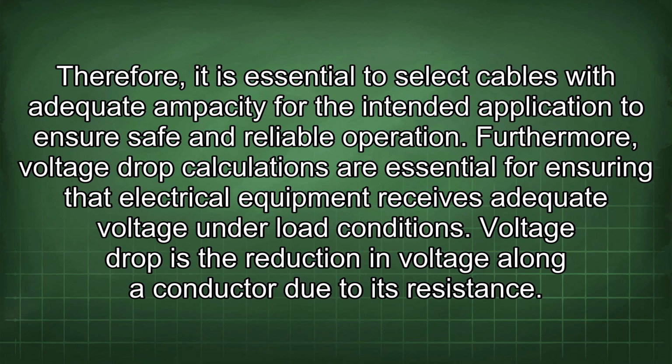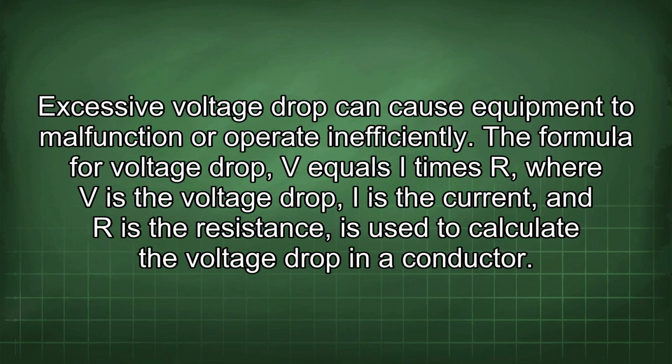Furthermore, voltage drop calculations are essential for ensuring that electrical equipment receives adequate voltage under load conditions. Voltage drop is the reduction in voltage along a conductor due to its resistance. Excessive voltage drop can cause equipment to malfunction or operate inefficiently.